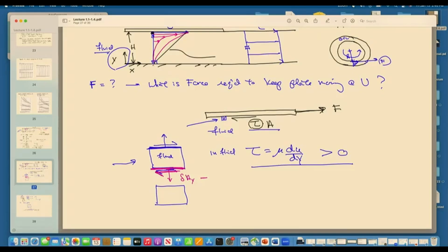No, right? Because if the lower plate was my hand and there's fluid moving past, although the fluid element at the plate is 0, attached to the plate, the shear stress is not proportional to the velocity, it's proportional to the velocity gradient. So the du dy, there is a value of the du dy, and in fact, that shear stress at the lower surface is the same value, right? We already said that the shear stress is constant.